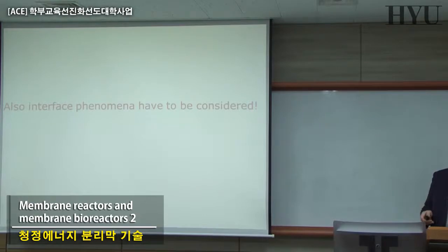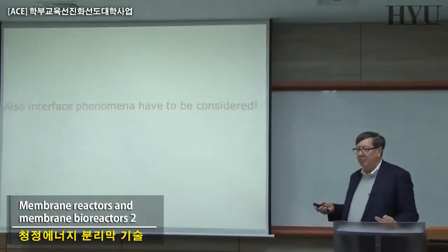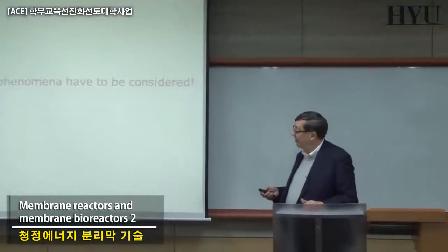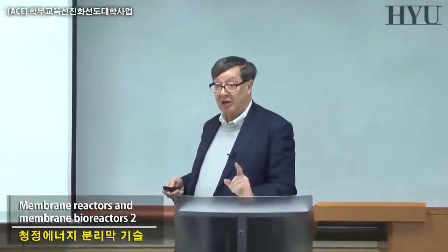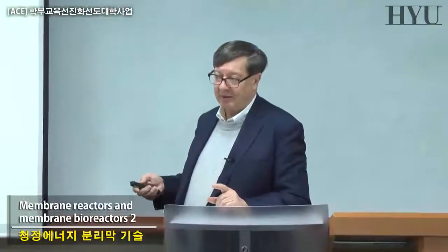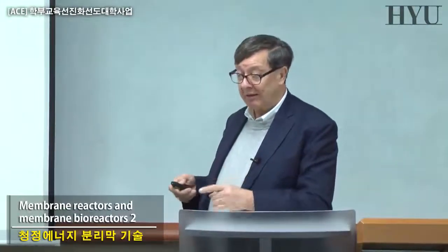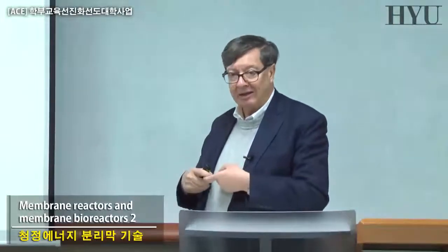Remember that we were mentioning that normally in a lot of studies, people define the properties of permeation in gas separation systems without considering too much the kind of phenomena that we have been describing with attention, spending some time on the liquid phase, that we call concentration polarization, fouling, etc. And remember that fouling and concentration polarization are not the same, but they are interrelated.